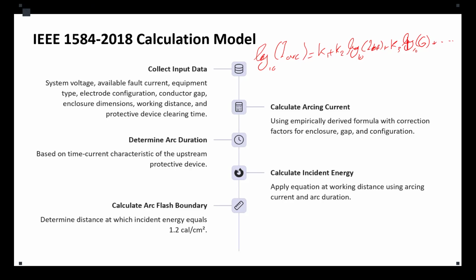Okay, you have to use conservative estimates. Always choose the longer of the two durations, one based on the standard arcing current and the other on the minimum arcing current. Whichever is longer for clearing the fault, you need to consider that.